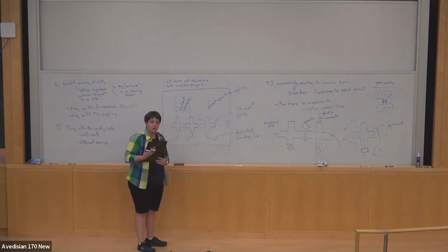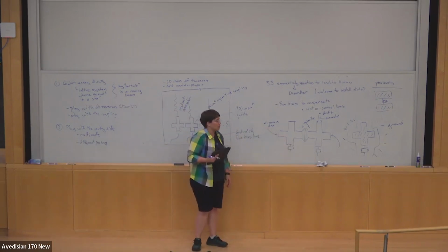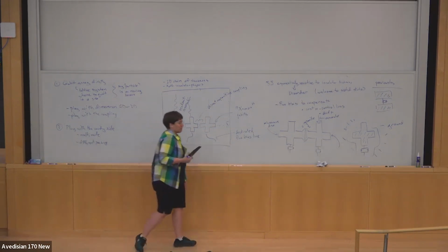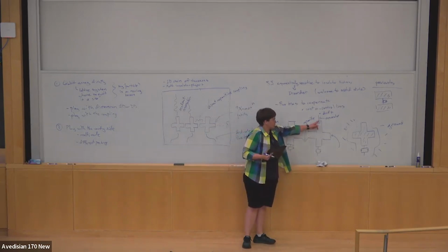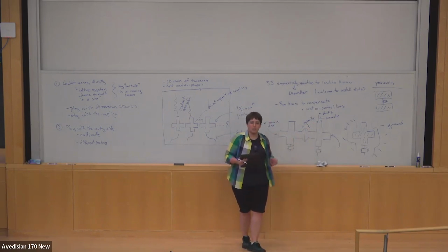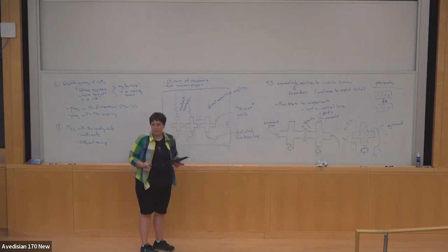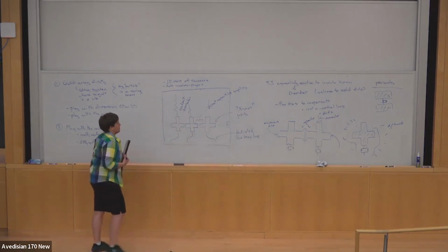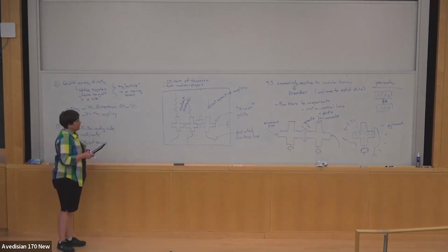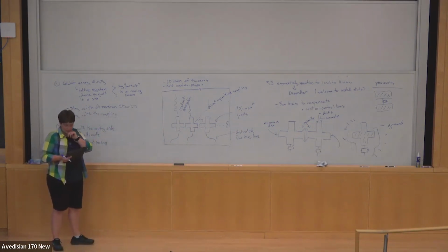But one thing that I should warn you about is that this device is well sub-wavelength. And so we live not in the world of parallel plate capacitors, but in the world of fringe capacitance. And so you will usually find that there's a non-negligible capacitance from, say, over here to over here. And so it looks very separated, that this arm is for this, and that arm is for that, but it ends up being a more tangled mess. And so you have to be careful with finite element simulations if you're actually going to do this. Okay. But it's a very common shape and it definitely has its uses.